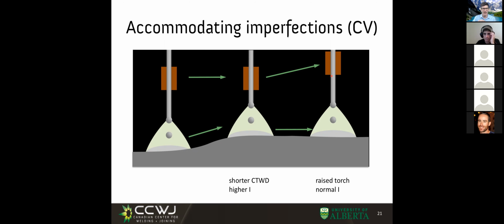The layer height can be irregular or can have different height of bead. You know how they detect that? They detect it using exactly this. That's a current patent. You could generate a patent like this now, right? They measure the current, and that way they know what their contact tip to workpiece distance is.